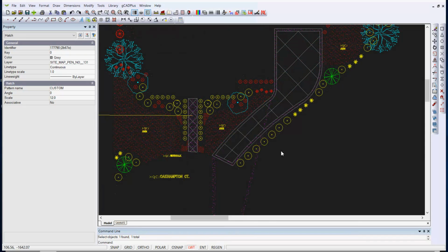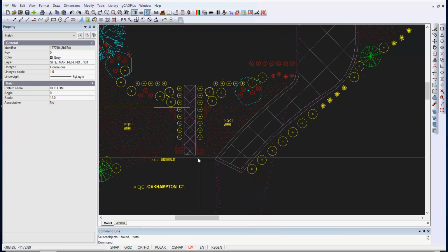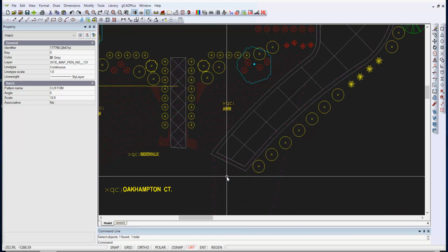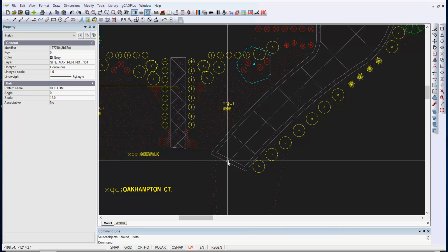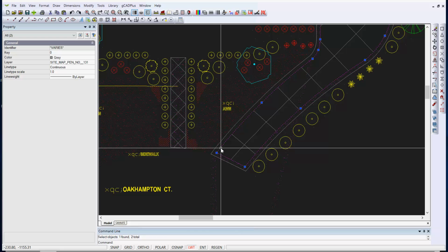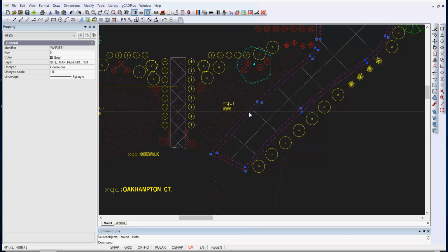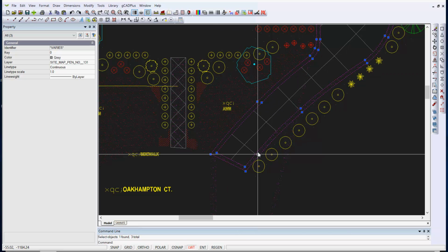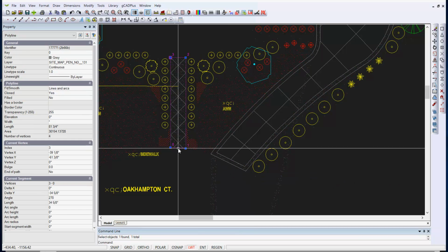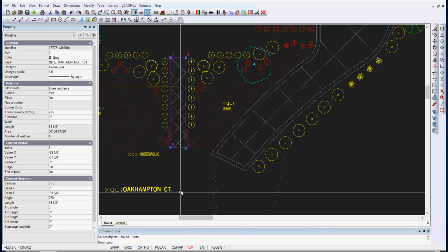Well, as a small aside, that errant hatching that we saw, which runs all the way across and backwards and around, also extends to this path area through here. Now, I'd be inclined to remove it straight away, but before doing so, it's going to be quite an easy job in gCADPlus to hatch it, because there are 2 polylines for that edging area that's easy for us to hatch, and there's another polyline here, and we could easily hatch in there.